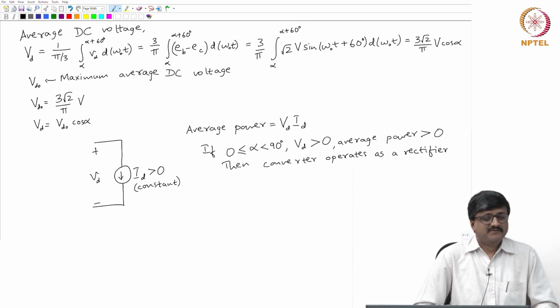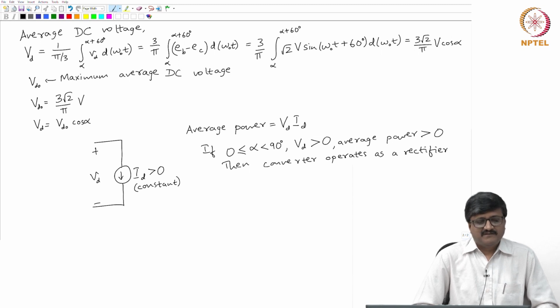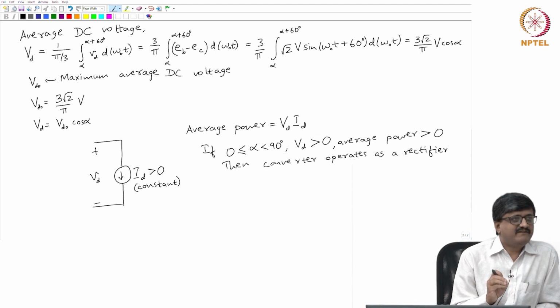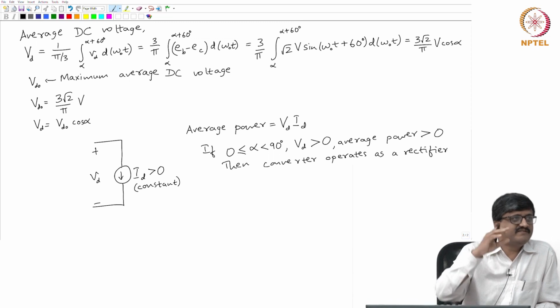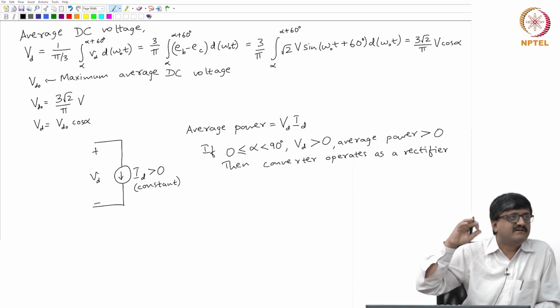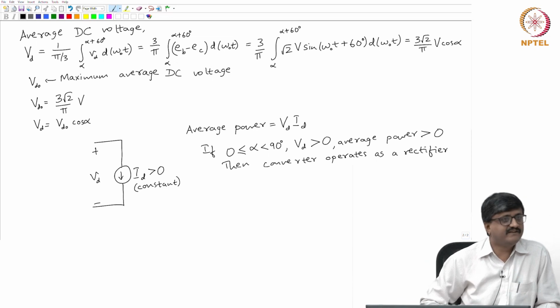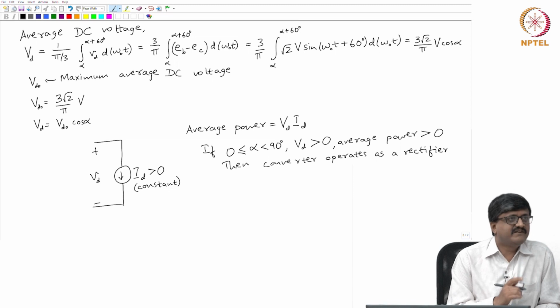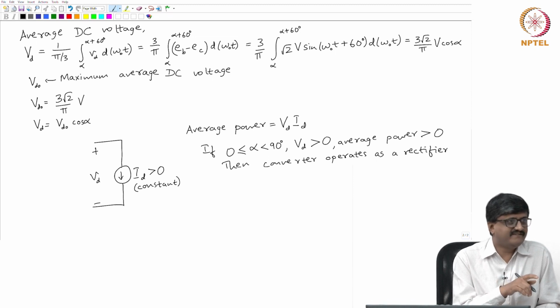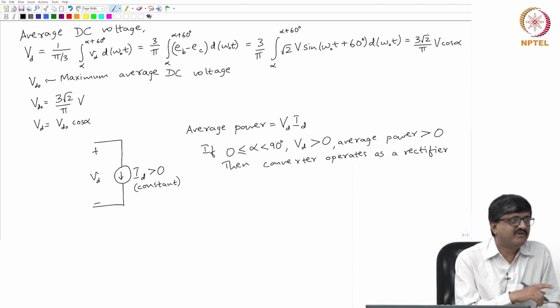Yeah. So, finally, it is some frequency which is appearing and which should not be there. Say on the DC side we want only DC quantity, but there are other periodic waveforms appearing on the DC side in the case of voltage. On the AC side as well we want only the fundamental, but we do not have DC on the AC side, but we have some other harmonic components.